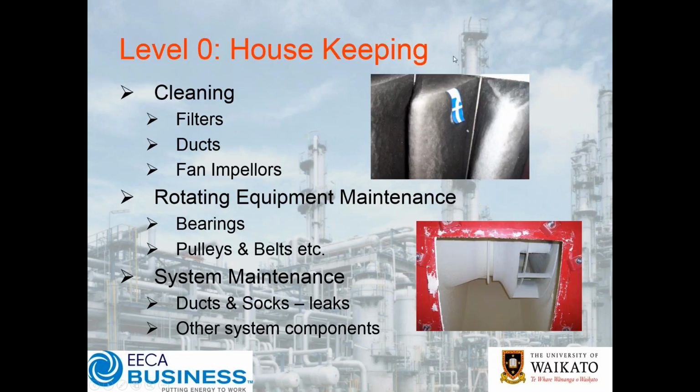So level 0, as we mentioned, housekeeping. This is something you do as you walk through your plant or your facility. What's the status of your filters? Are they looking a little black? Are they looking a little dirty? Is there a record kept of when the last time they were changed? Have we got sufficient pre-filtering going on, especially if you've got dusty environments?